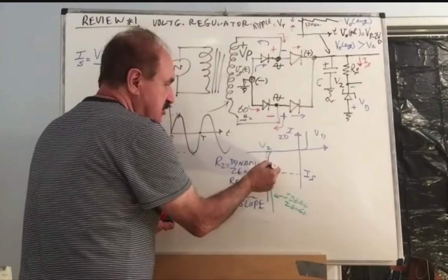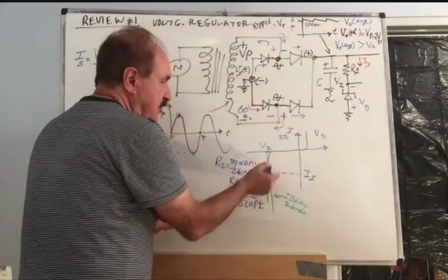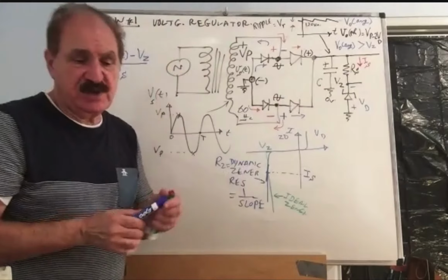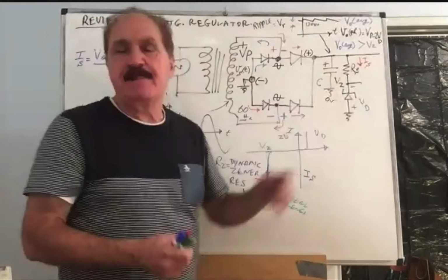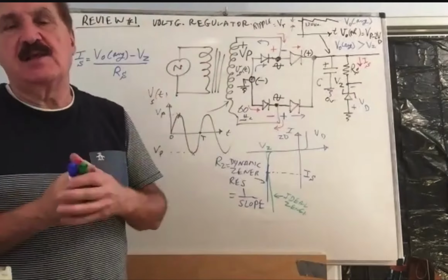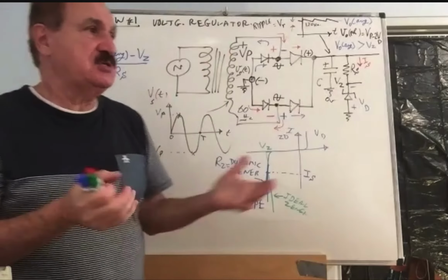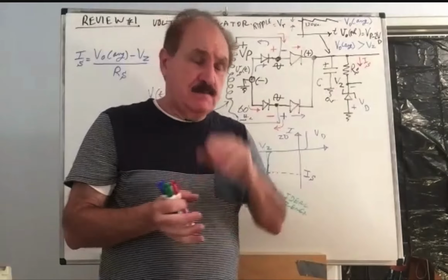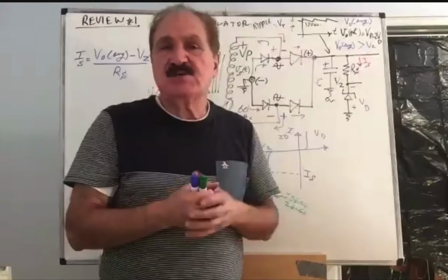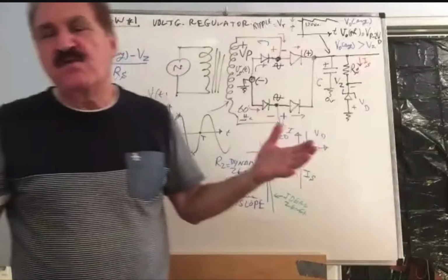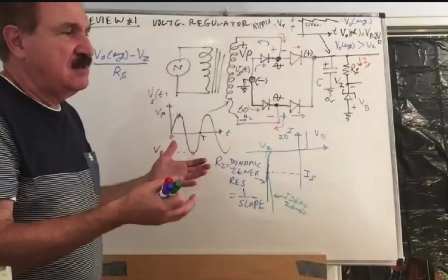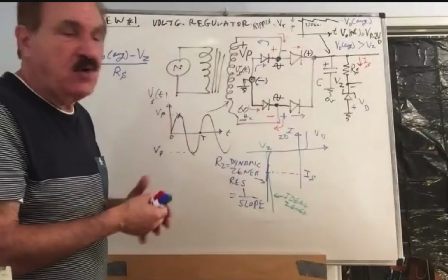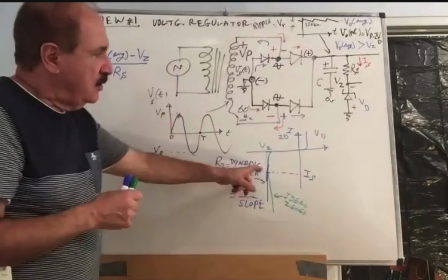So it is like this. You need to calculate that slope from the characteristic, or often just the manufacturer will specify what is their typical Zener resistance. For example, they will say Zener resistance is typically 5 ohm, 4 ohm. It is usually very low, but it can be even 10 ohm or 15 ohm. It's possible.